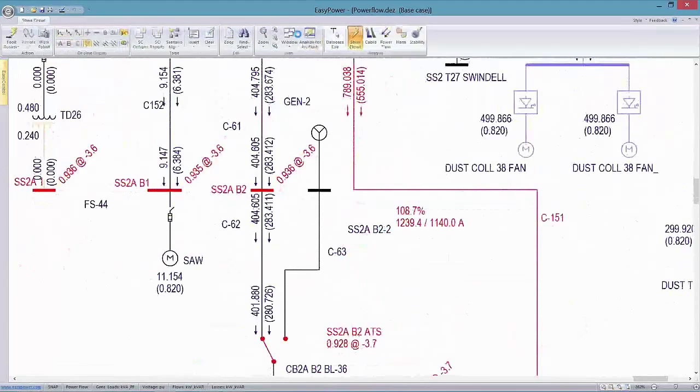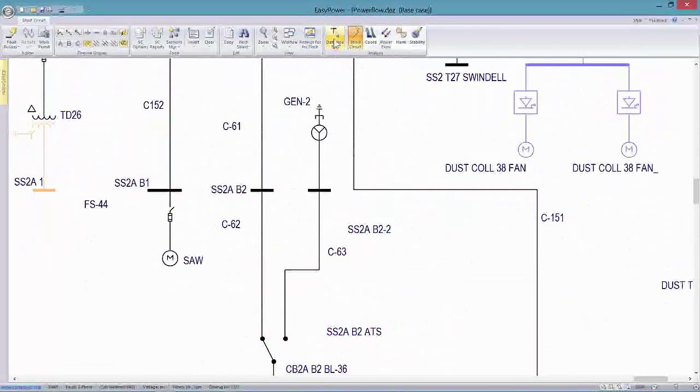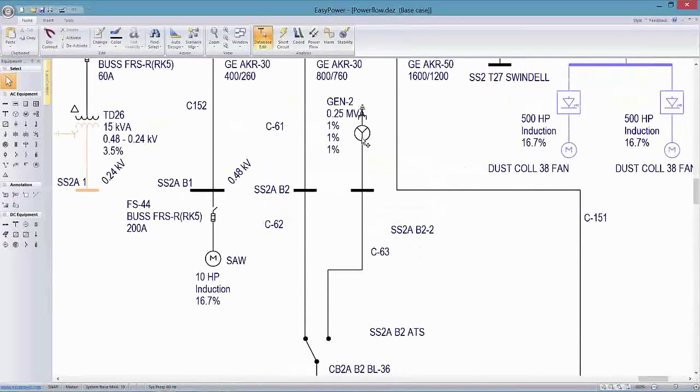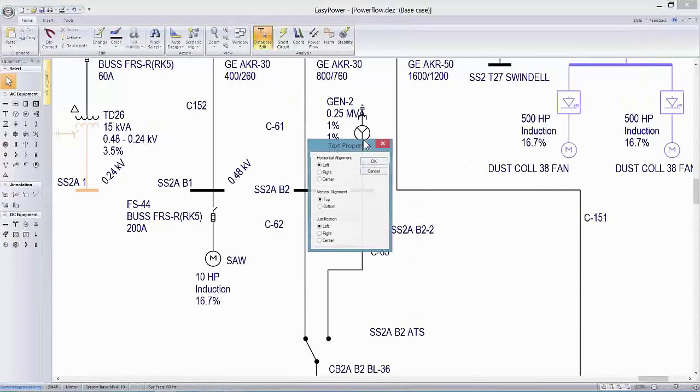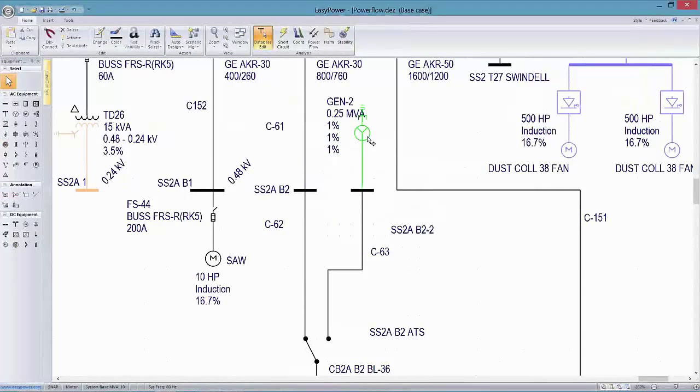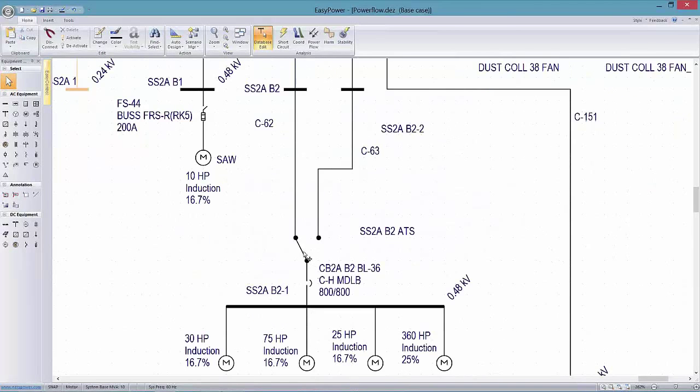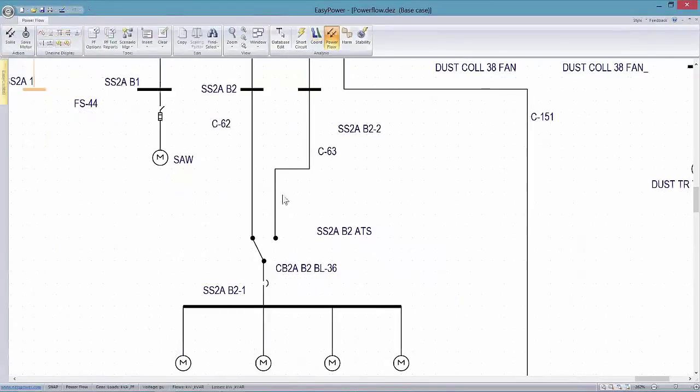All right, so the point I'm trying to make is, in setting up the generator data dialog for power flow, it would have to be a swing system so it can react to changes in the load and supply both reactive and resistive or fixed loads.